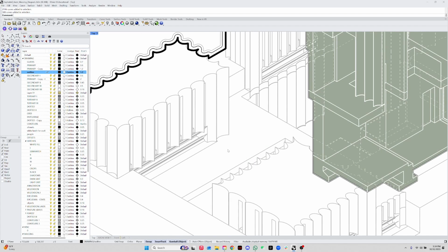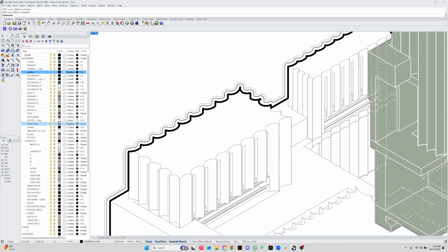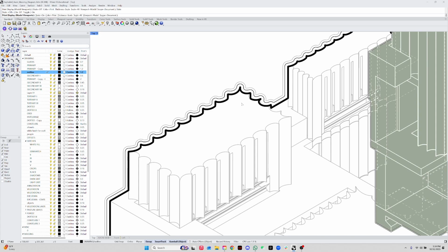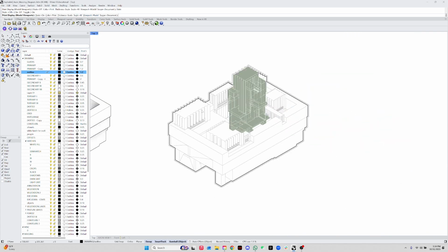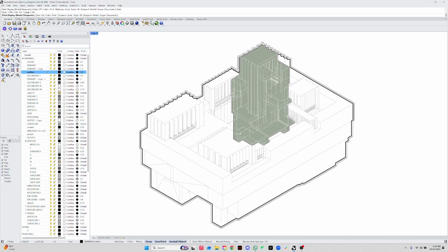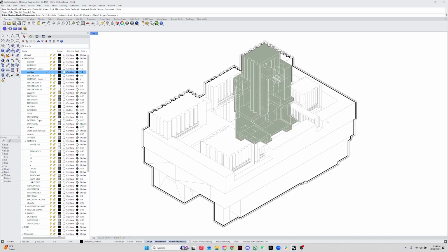As you can see, my line weight, I'm using the template that I gave you guys, and I have my print display on right now. If I do print display, that's how I have my line weight on. If I turn it off, then you go back to regular lines. If I go back on, then the line weights turn on, and I have a scale of 40 right now, at least for my window that was working, depending how big your project is. But this project is relatively the same size that you guys have your row homes.